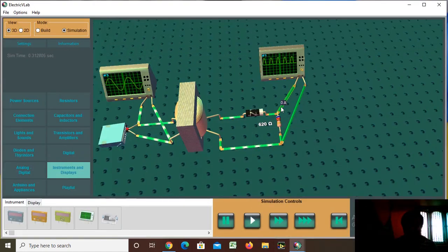What is the advantage of the half-wave rectifier? The circuit is very simple. We are using only one diode. Cost-wise, it is very less. You can easily design it. But there are some major drawbacks. You can't use a half-wave rectifier to design a power supply, because in a power supply you need a continuous signal. But here, in the case of the half-wave rectifier, it converts for the positive half cycle, and for the negative half cycle you are not getting anything. So that's the disadvantage. Because of this reason, the efficiency of the half-wave rectifier is very less.